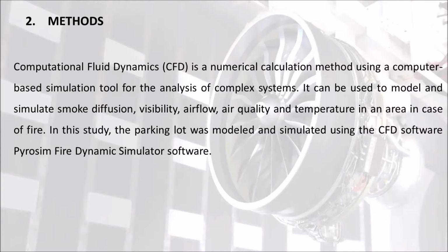Actually, we used computational fluid dynamics software. It is a numerical calculation method using a computer-based simulation tool for the analysis of complex systems. And also, it can be used to model and simulate smoke diffusion, visibility, airflow, air quality, and temperature in an area in case of fire. In our special case, the parking lot was modeled and simulated using the PyroSim fire dynamic simulator software.